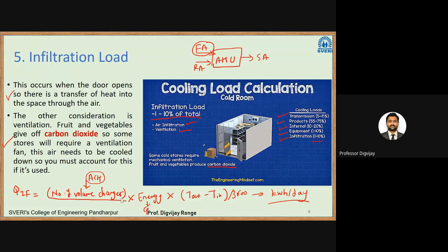The loads we have seen: transmission load, product load, then internal load, then refrigeration system load, and the fifth one was infiltration load. So I have to consider all these loads, then calculate the total load acting on the system, and then design a refrigeration system.